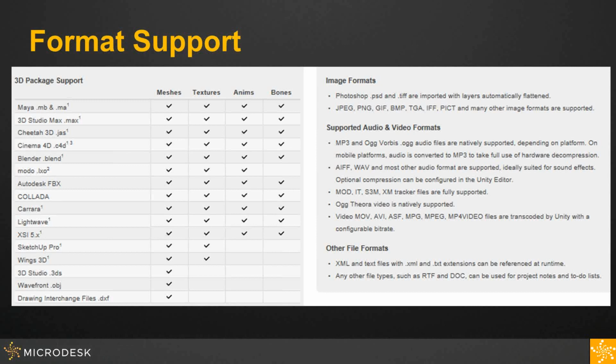For what we're going to be focusing on, we're going to show you an example of taking content from Revit and bringing it straight into Unity. We're going to be using the FBX format. Part of the reason is, number one, it's very easy to keep an FBX file inside of an Autodesk product and maintain all of the materials and information that you've assigned. So if you put in things like lights, materials, data, you won't lose it. You won't have to reassign it. And also, it's perfectly set up across the entire board. All these different things work with it.